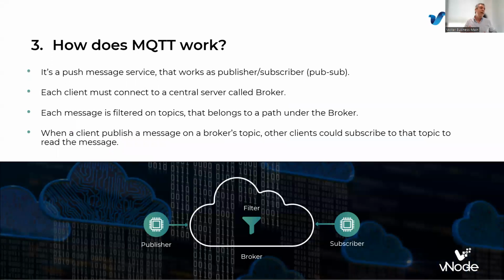So how does MQTT work? On one side, you have a software or a firmware, actually a hardware, whatever it is, with a firmware inside, or any kind of software. It doesn't matter. It could be software in a computer or a firmware in an embedded device. This software or firmware can work both as a publisher or as a subscriber. It gets data from whatever it is and then pushes this data to a broker.